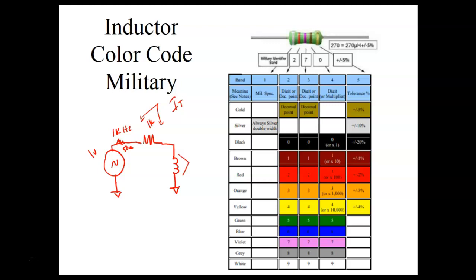In a communication system, to get the maximum power transfer from the source to the destination, all the impedances in the circuit have to match. We call that impedance matching. The coax cable that runs into your computer, if you're at your house, is a 50 ohm cable. All the amplifiers down the whole line are matched to 50 ohms. You do it like that, you're talking to me now.